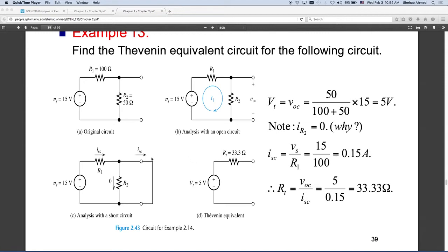If we apply that trick here, it's as if this voltage source is providing a voltage of 0. A voltage of 0 means it's a short circuit. So I will place a short circuit instead of this source, and then I end up with what? These two resistors are series or parallel? Parallel. Remember, my two terminals are here. This is one terminal, this is my other terminal. I want to find the equivalent Thevenin resistance between these two terminals.